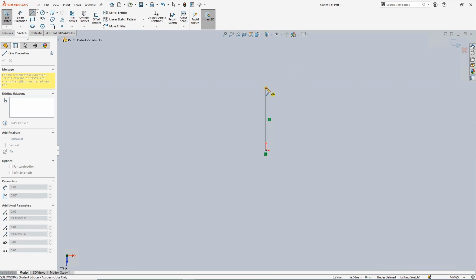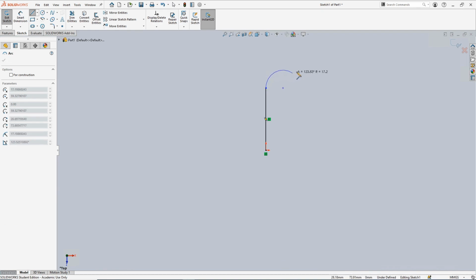You see just right next to the mouse cursor where it changed to a pencil, we have two concentric circles. So once we see that, we can move it out again, then it would start drawing a tangential arc to our endpoint of the line.